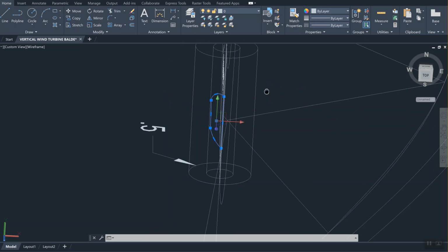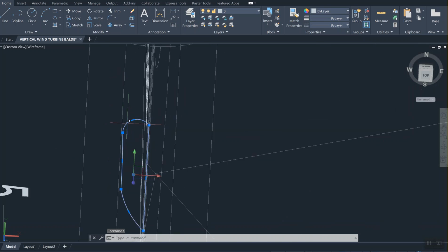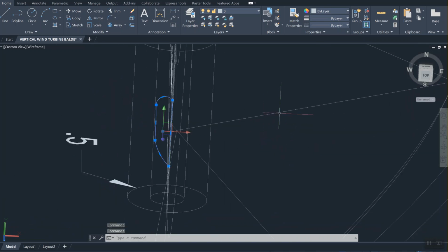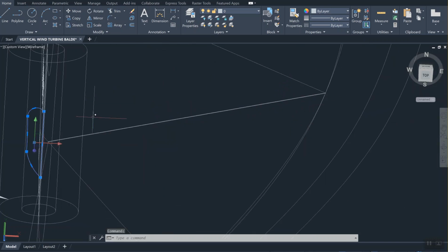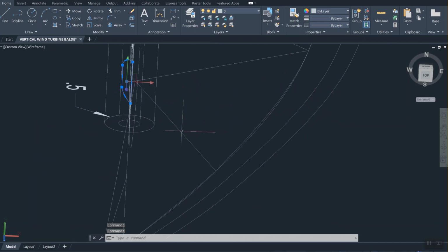I need at least 2 copies of this for each extrusion alongside this line. I keep saying extrusion, but the command will be the loft command. So you need 1 loft here, and perhaps another loft at the end of this line. For each loft, you need at least 2 copies, 1 here and 1 here.